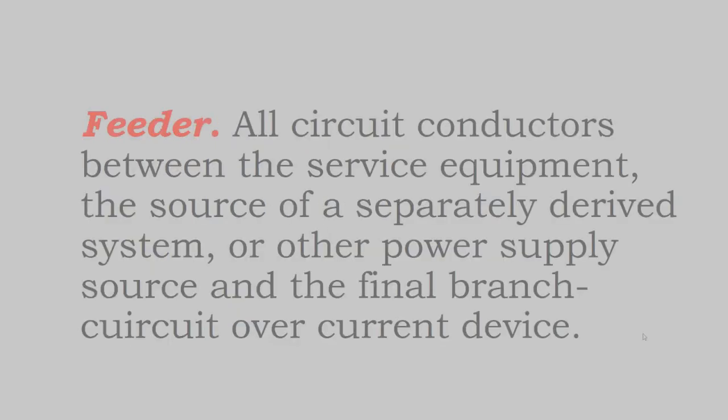All right, let's define a term. Feeder: all circuit conductors between the service equipment, the source of a separately derived system, or other power supply source and the final branch circuit overcurrent device. So what we're talking about is anything between the generator and the breaker switch on the panel that the generator provides.